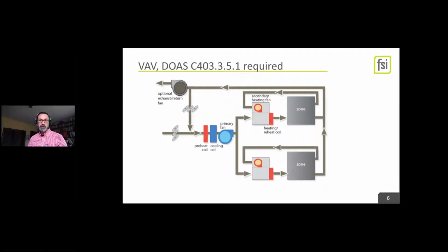You will definitely be replacing, if your building is more than a couple years old, the control system. Either the heating, including the box heat and the RTU heat, or the cooling system has to be hydronic. And we thought we were going to do more high performance VAV when we got that provision in the 2015 code. And honestly, we have done, I think, 2 of them. And we did them on the chiller side. So we had a chiller connected to the rooftop units. It limited the hydronic side.